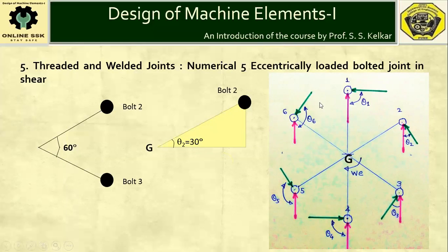So here the green colored arrows are shown, which represent secondary forces and which cause the anti-clockwise rotation of the bracket, because externally applied load causes clockwise rotation and secondary force should cause opposite anti-clockwise rotation of the bracket. Therefore secondary forces will be in direction as shown by these green arrows. Now here, due to symmetry, value of Fp1, value of primary and secondary forces will be same.